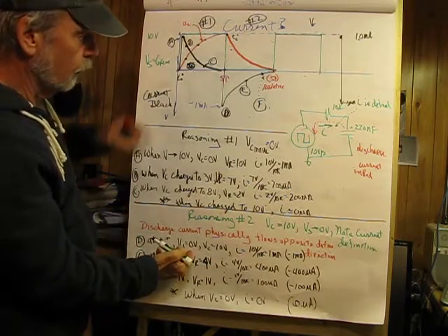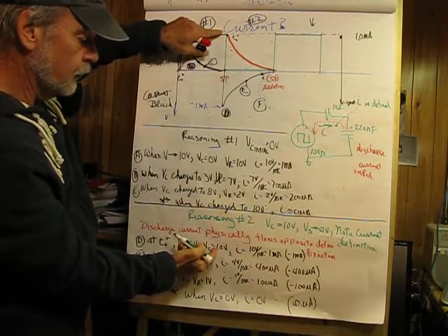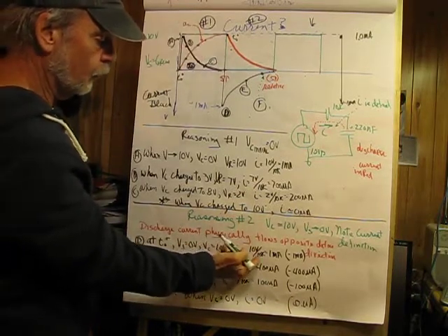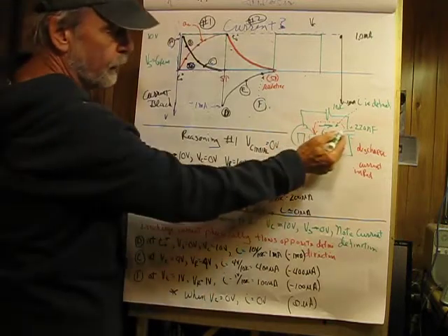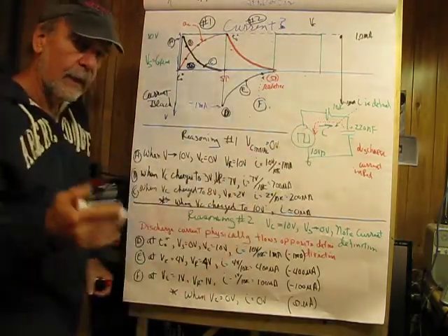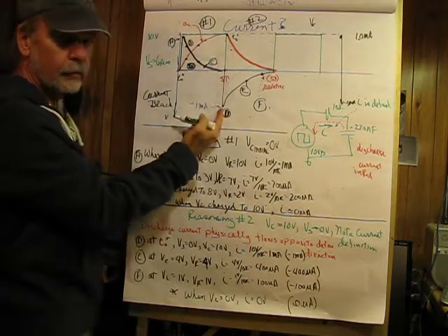Source voltage is 0 volts. That makes sense. DC is 10 volts, fully charged. I is going to be 10 volts divided by 10K equals 1 milliampere. And since the physical current flow is opposite to the defined current flow, what we get is a negative 1 milliampere.